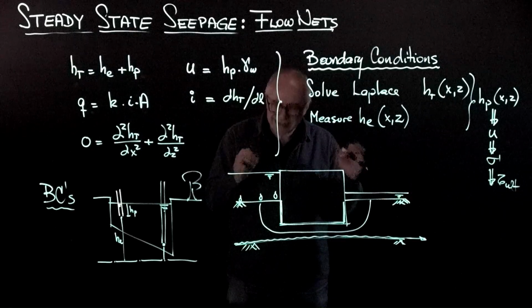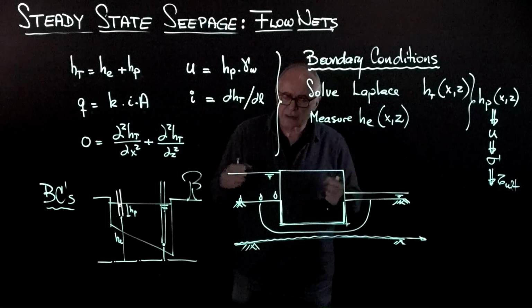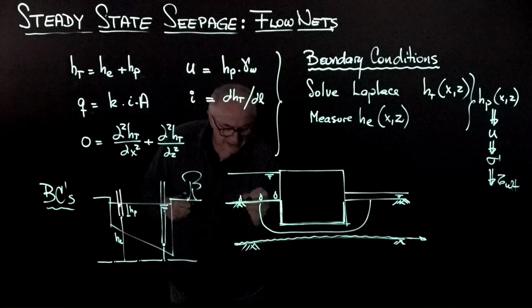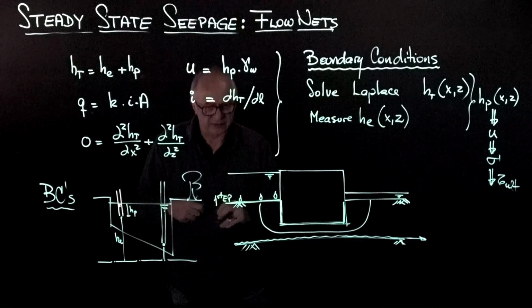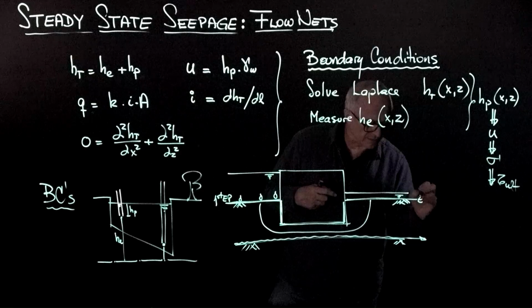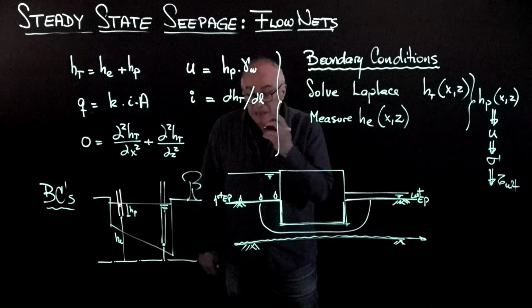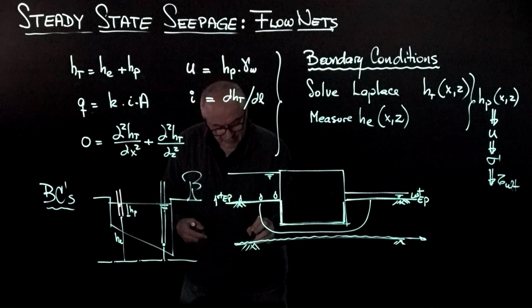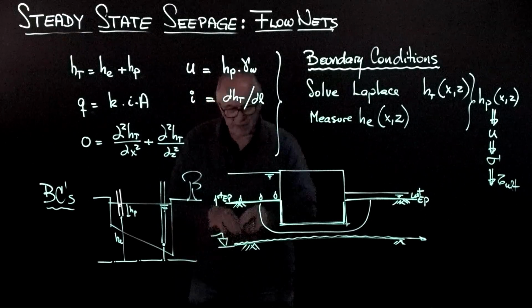So if you can feel where that water molecule will go and the trajectory that it will drive, you will recognize right away that this is the first equipotential, total energy, and that this will be the last equipotential, the last one. And by the way, we know the energy on the first equipotential because I can take the bottom here as the datum from where I measure all the elevations.